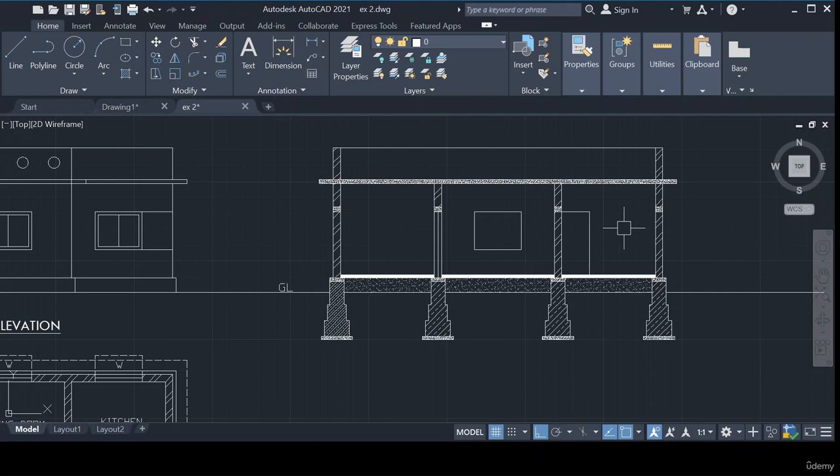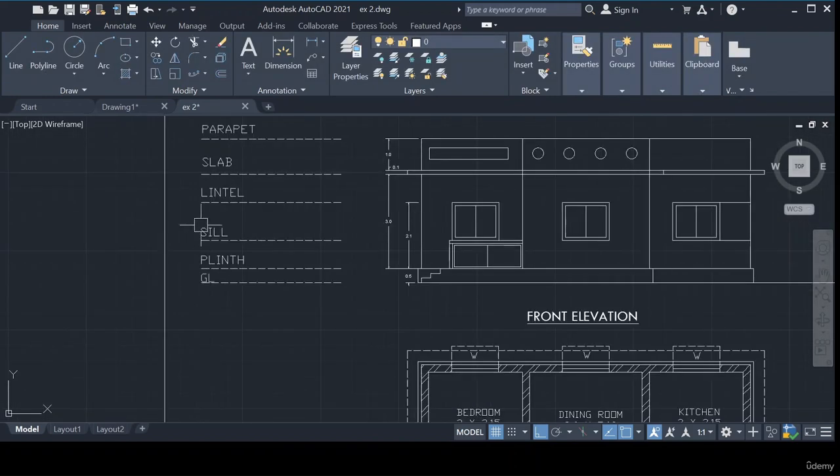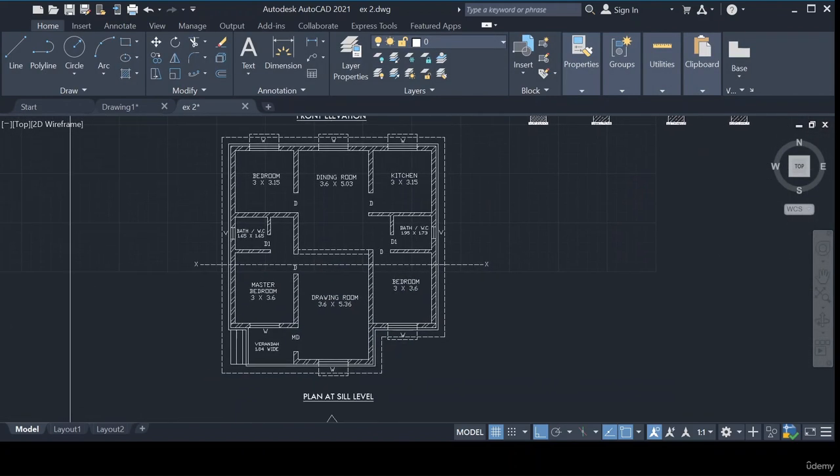Now we need to show the dimensions, and we need to give the namings for this one. Okay, I just show the dimensions here. I go to the dim style, modify, primary unit 0.0. I just take text, I just reduce 0.1. I just take arrow size also 0.05 because the size is little. So here also you can easily use one.